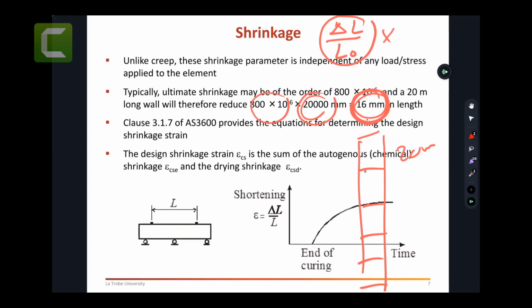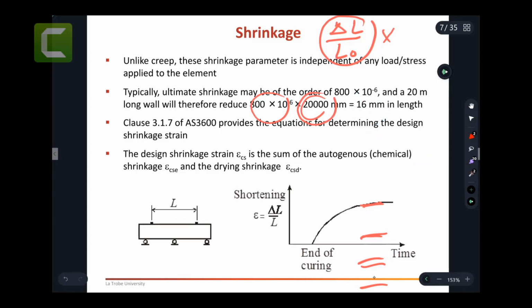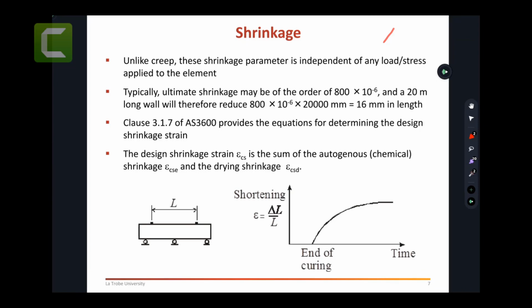Then the solution, as I said, if it was on the ground, then you can use saw cuts with some steel. If it was only suspended, then you can only rely on the steel to resist such cracks. Okay, that's if it's suspended. Now, I think you're going to know from industry, the typical length of concrete people pour as suspended goes up to 30 meters. Then after this, they have to introduce some movement joints. Okay, so they will have two separate slabs.